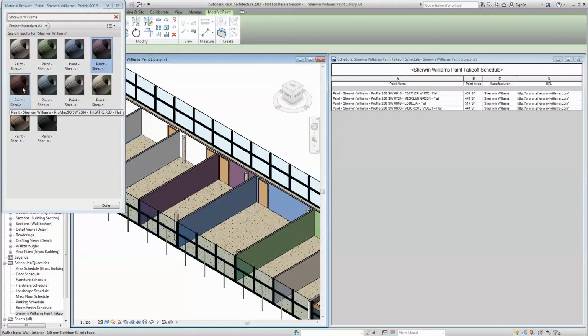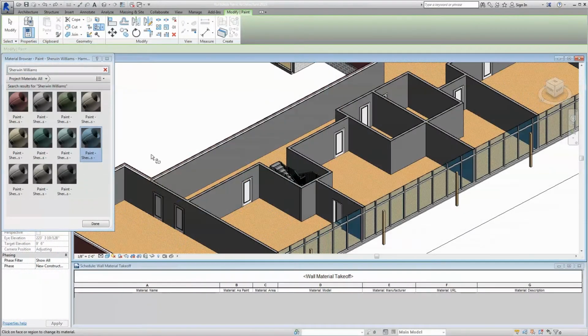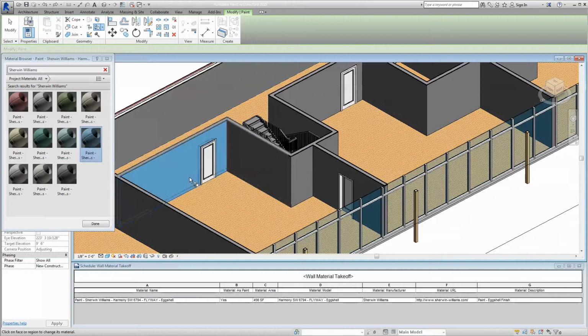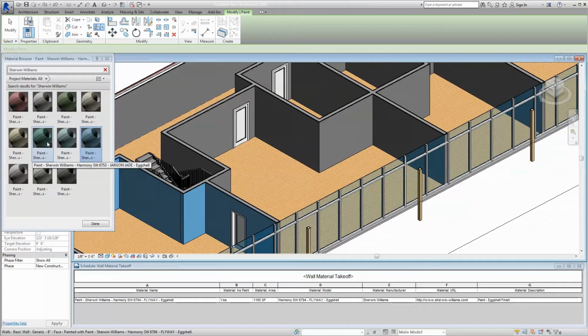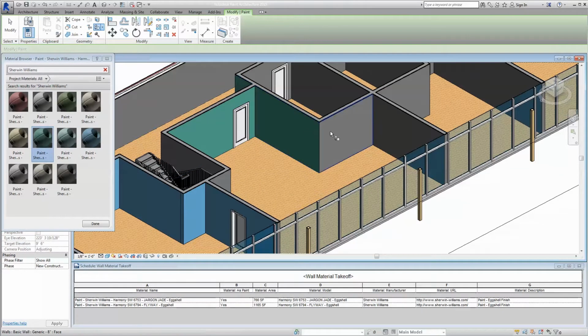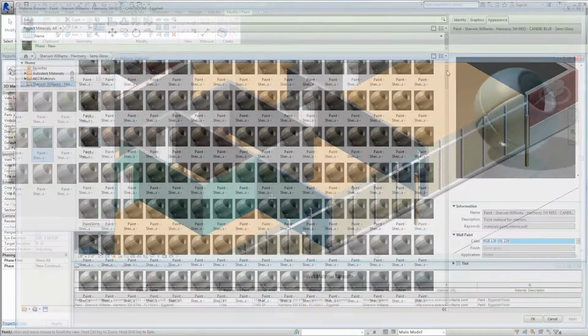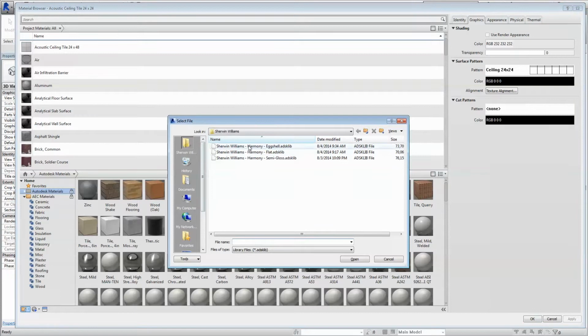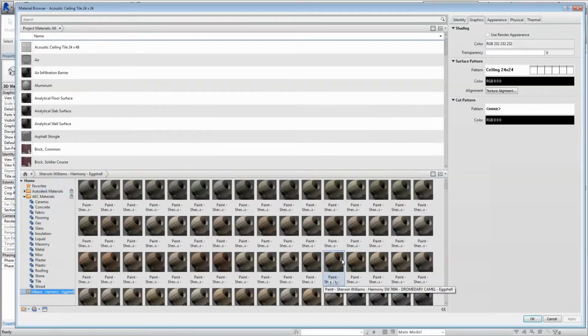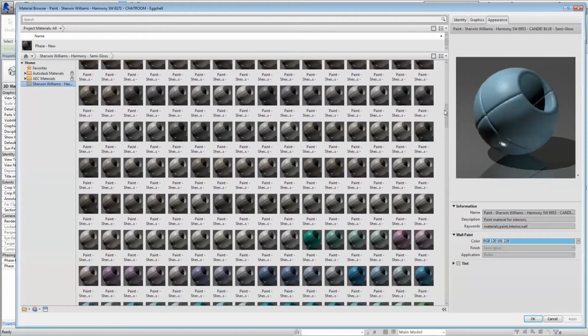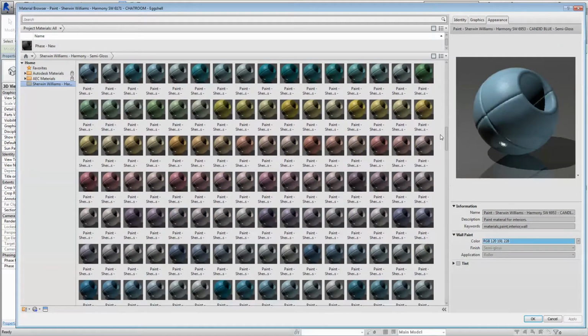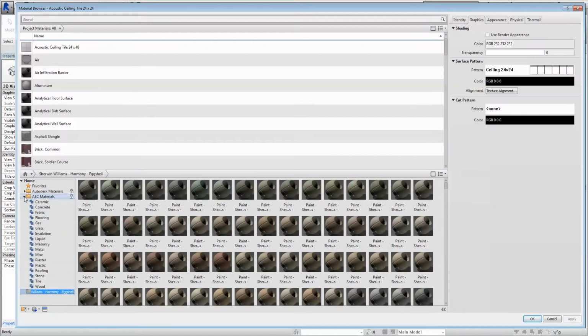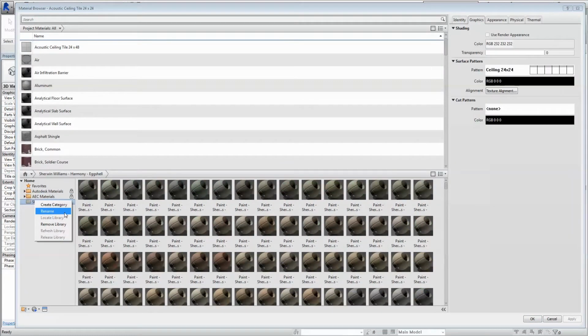Your Autodesk library files are stored locally on your machine or on a centralized network for access by multiple people or project teams. Such a structure allows you to make revisions to the library once and easily implement them across multiple projects, utilizing the same materials library. The Autodesk library file loads right onto your Revit model for easy access to every color you might need. With the library, you have the ability to import only certain colors or entire color families and palettes in order to meet your specific project needs. You can even rename the library as you see fit for your particular project.